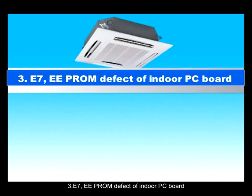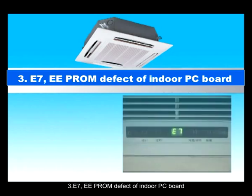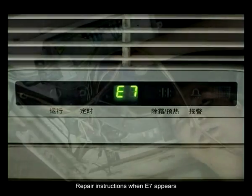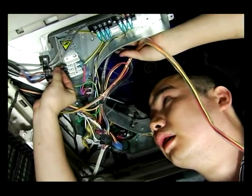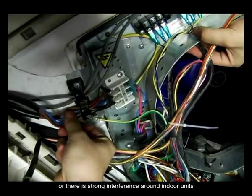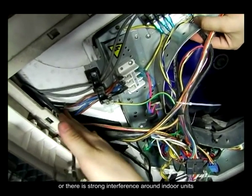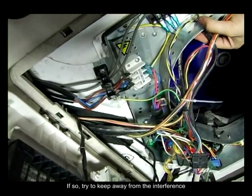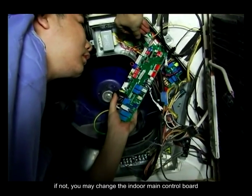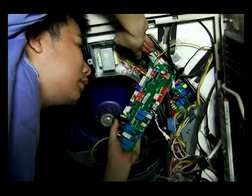3. E7, PROM. Defect of indoor PC board. Repair instructions when E7 appears. Check if the electric control wiring is reliable or there is strong interference around indoor units. If so, try to keep away from the interference. If not, you may change the indoor main control board.